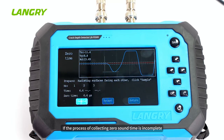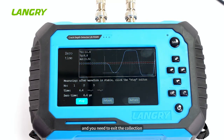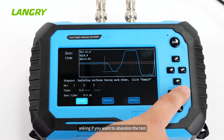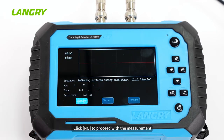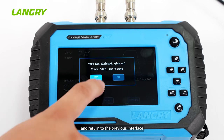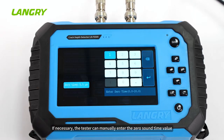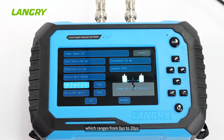If the process of collecting zero sound time is incomplete, and you need to exit the collection, a prompt box will appear, asking if you want to abandon the test. Click No to proceed with the measurement. Click Yes to cancel the current sampling, and return to the previous interface. If necessary, the tester can manually enter the zero sound time value, which ranges from 0 microsecond to 20 microsecond.